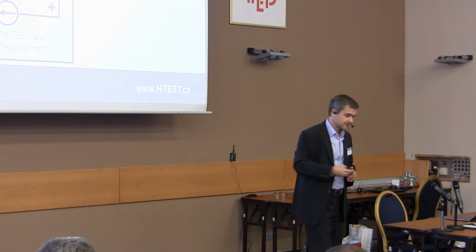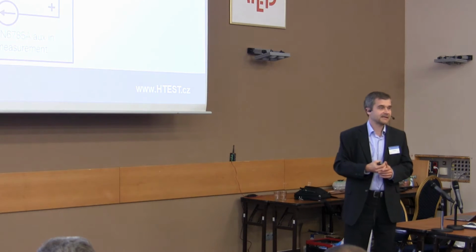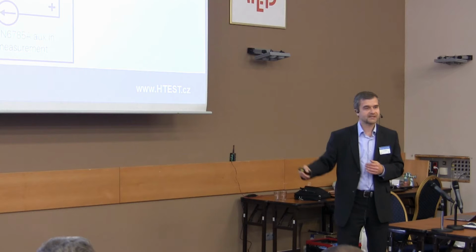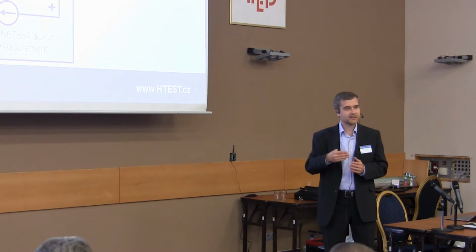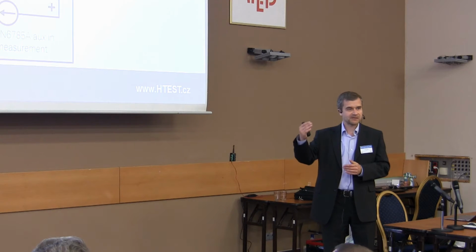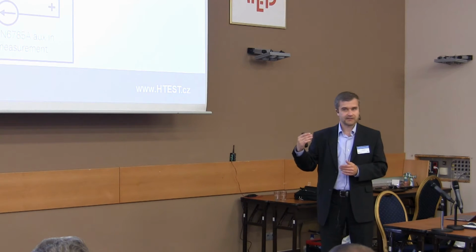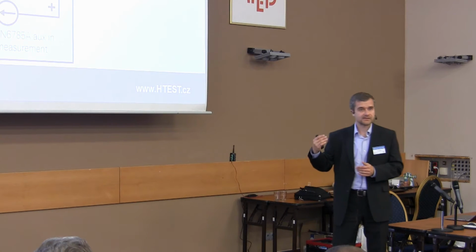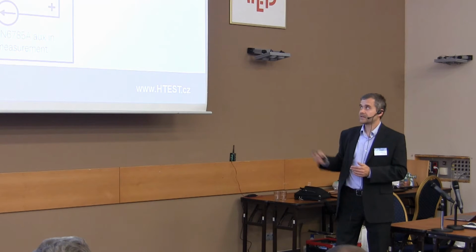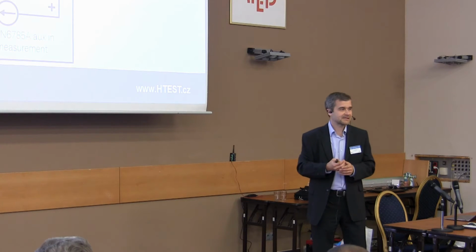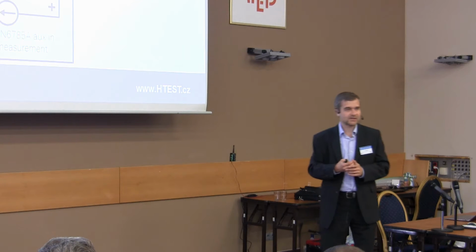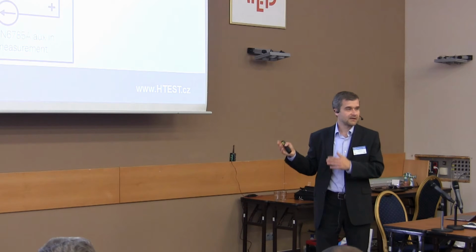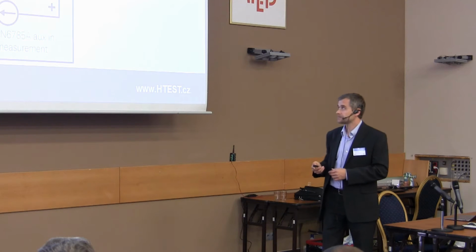With this you can do a battery rundown test, a long-time measurement, where you look at which point the battery is below threshold and the device turns off. You can select several batteries with different chemistries to find which has the best results for the device you want to test.